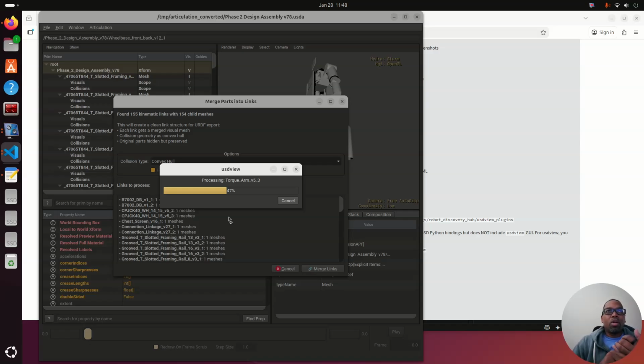And so when we talk about robot sim to real, that is one of the biggest issues: we've simplified the robot down in the URDF file so much that we've lost some of the detail. And when we go back and send commands to the real robot, it doesn't respond in the same manner as a simulated robot. So obviously that's something we take into concern in our robot control hub. We do a true up, the real robot versus the simulated robot.